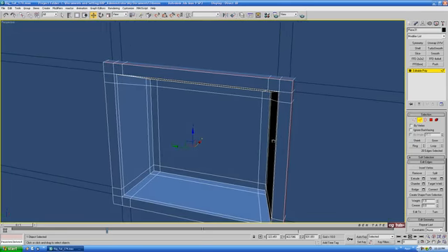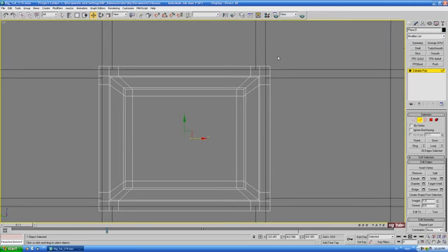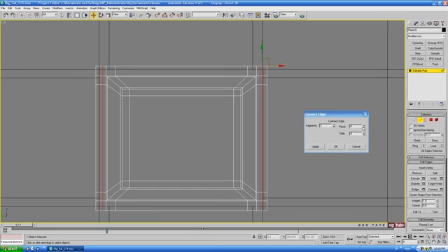And we also need a few on the front here, so let's just maybe do these ones in the left view. Let's grab these edges here, we'll do a ring. Let's actually do both sides at the same time. And we'll connect it up again with 2 segments. And just slightly pinch them out a bit. We don't need it to be too sharp. Let's do maybe about 40 or so on the pinch. And the exact same thing horizontally. Ring those and connect them up.